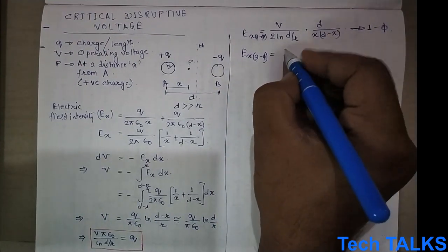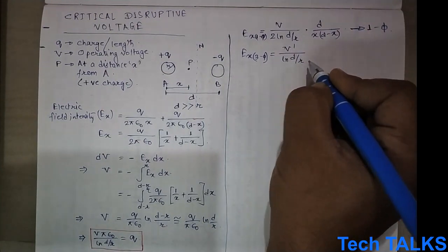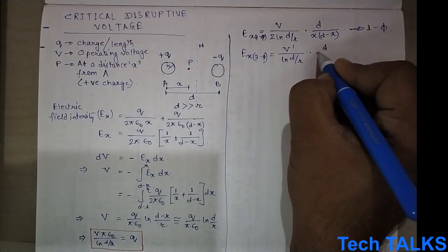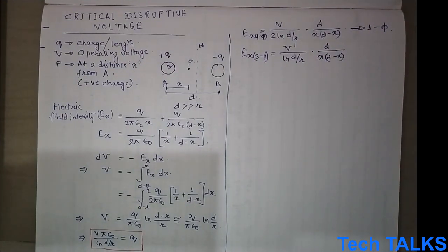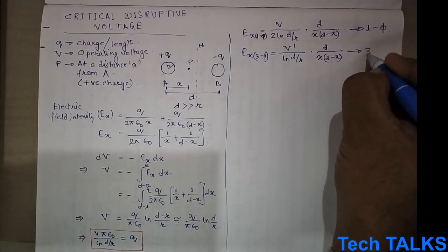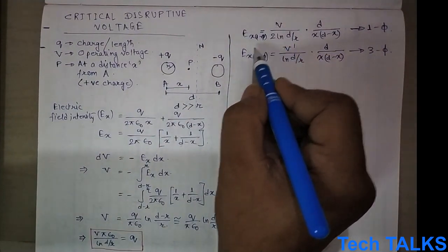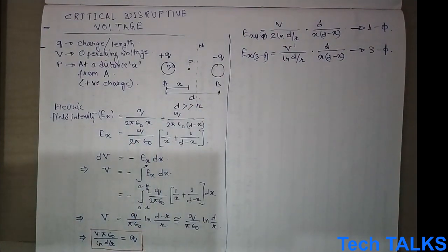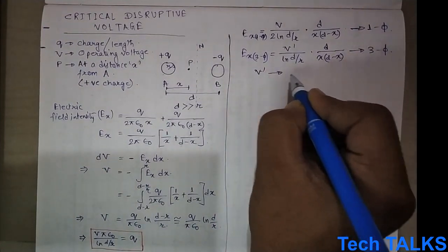Okay, this is for a three-phase system. And here V is the operating voltage, the voltage between two conductors. So in a three-phase system there are three conductors. So what is V dash? V dash is the voltage between line and neutral, mainly the phase voltage in a star connection.